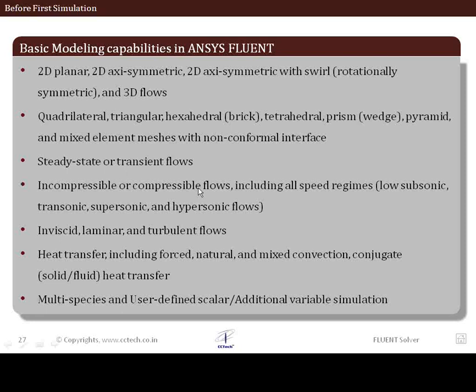Fluent has special features to capture highly compressible flows using its density-based solvers, by which you can capture really hypersonic flows, very high Mach numbers as high as 4 or 5, and higher even. And it can deal with the viscous effects using either an inviscid flow solver, which is basically an Eulerian solution to your problem, or a laminar flow in which the viscous effects are taken into account. And in another case, if the Reynolds number are a bit higher, or the Rayleigh number is quite high for a natural convection problem, we can also have turbulent flows being modeled according to some specific turbulence models. A variety of turbulence models are included. I'll speak about this dedicatedly in the lecture on turbulence modeling.